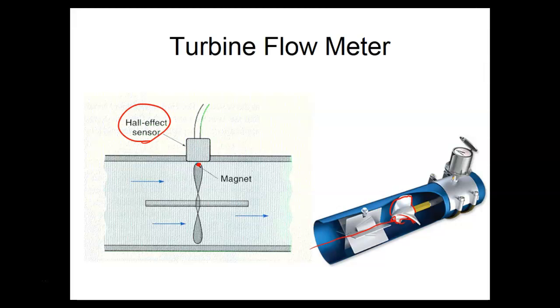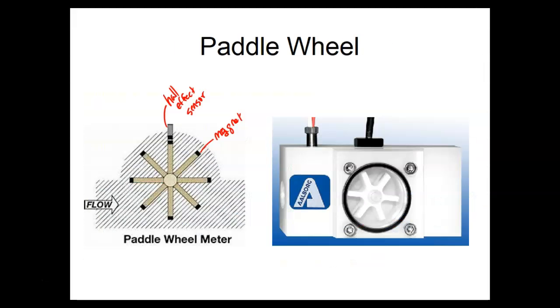So this one's pretty simple to see how it works. It gives us a digital output, and of course we could bring this into a programmable logic controller, and the controller could do the math to take care of the transfer function. What's nice about these is they don't have to be converted into digital to bring them into the main controller that we have in most systems now.